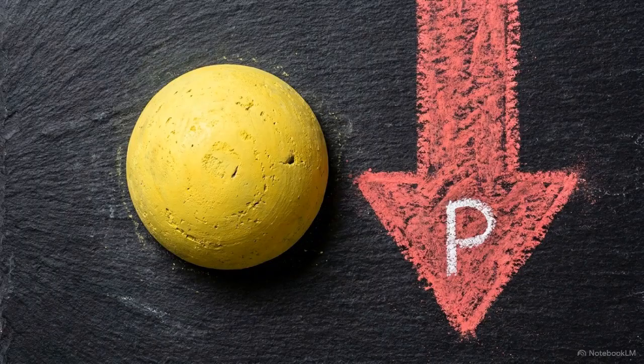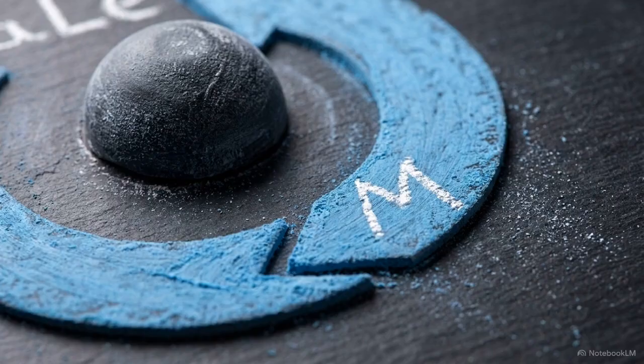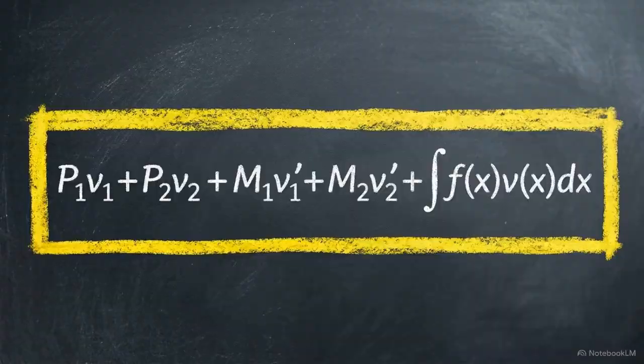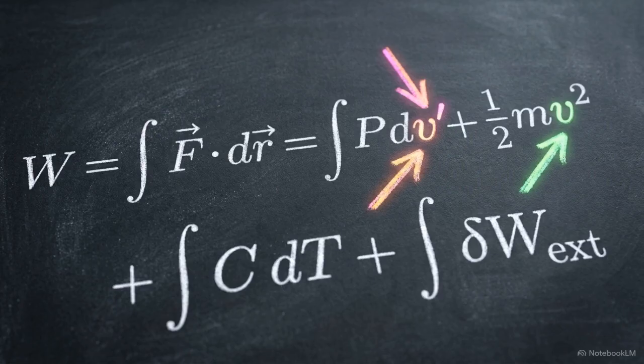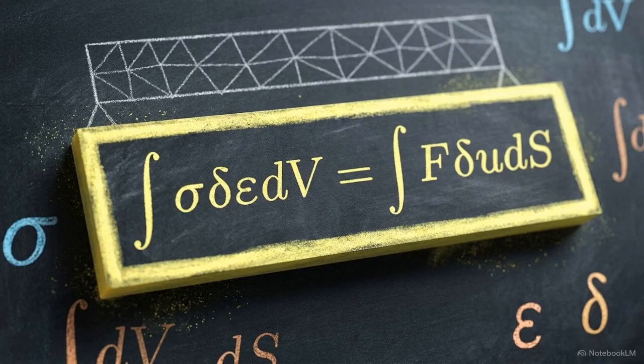By adding the modified point loads, the applied node moments, and the distributed expressions together, we get the complete equation for total external work, standardized entirely in terms of displacement and its spatial derivative. This establishes a single, unified mathematical target for the finite element formulation.